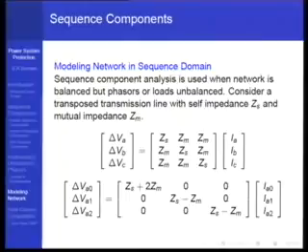So all your actual steady state analysis, what you have done in a computer analysis course, for example a power systems course, is all based upon positive sequence data, not per phase data. And usually here in modeling sequence, you take A phase as the reference phasor. If you change the reference phasor, the matrix structure will change.